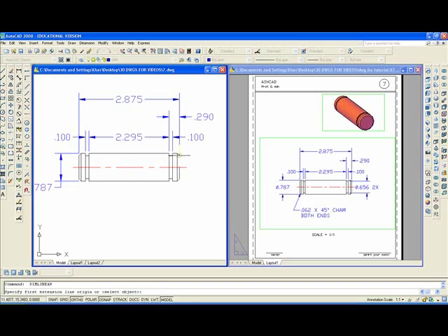And once again over here. That keeps happening with the dimension going down there. There's a way of fixing it. I'll figure it out later. In the meantime, what I'm going to do is take off Ortho, take off OSNAP, and I'm going to erase this dimension because the numbers are obviously wrong. And so I'm going to redimension that.